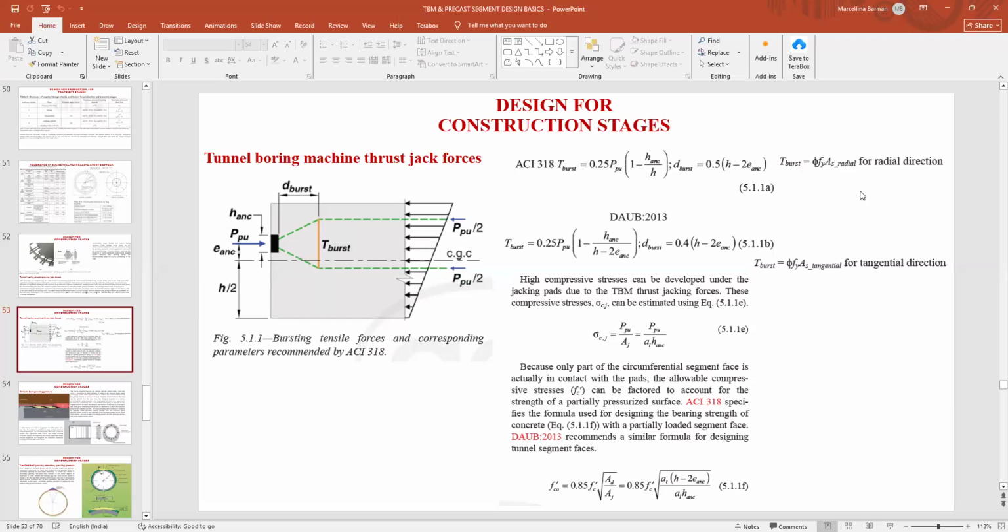So in the GeoConsole, whenever we are doing the design of the segments, suppose in a pre-bid project the client or the contractor tells me that I have a limit of 90 kg per cubic meter. So 90 kg means it includes all the main reinforcement, the secondary reinforcement, all these chair bars, ladder bars, and your busting reinforcement, everything combined. So your design should be in such a way that all the reinforcement is combined. This is not the same case when you are designing a beam and column. In the beam and column, you have main reinforcement and the secondary reinforcement.